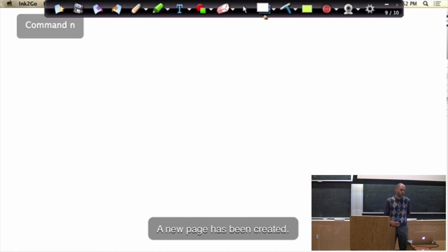Okay, as time expires here, it turns out the notion of partial feedback linearization is very general, right? So we did it in 2 specific cases. You can do it in general for the manipulator equations, right? So if I write down in general, I have my manipulator equations that look like this. Let me even simplify it. I'll lump C and G together.